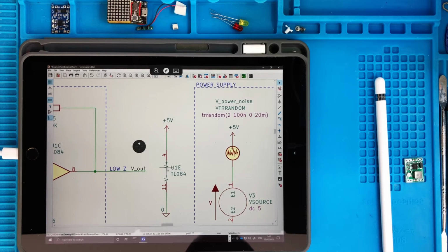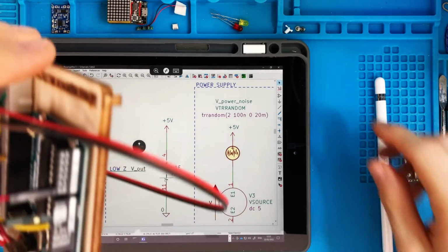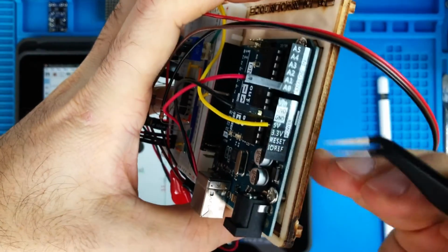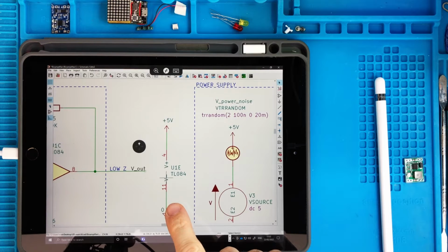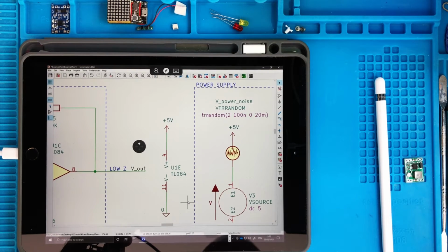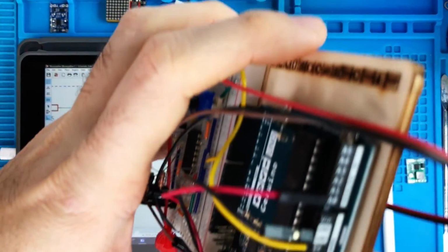Pin 4 is connected to the V+, which then is connected to the 5 volts of Arduino, which is this power port we see here, the 5 volt, while pin 11 is connected to V-, which is connected to this symbol, the symbol of ground, which means the negative pole of the battery, our 0, let's say.